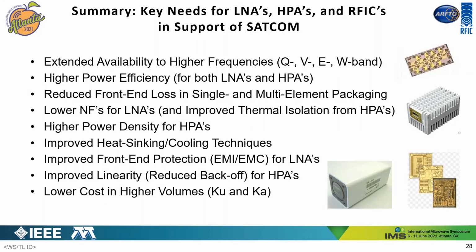Lower noise figures are always better than higher noise figures for LNAs. And I mentioned that the LNA noise figure is highly leveraged in the size and cost of the system. And of course, the LNAs themselves would prefer to be in a cooled situation. So we need to improve thermal isolation of the LNAs. We like to keep them cool and well isolated from any heat generated from the HPAs.